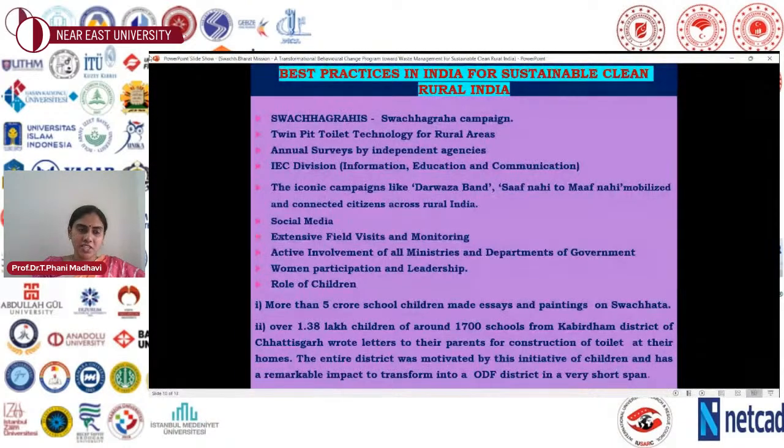Both pits are connected with a junction chamber at one end, and the pit walls have a honeycomb structure, and the bottom of the pit is earthen. Depending on the number of users of the toilet and the size of the pit, it will vary. The capacity of each pit is kept for a duration of 3 years. So the first pit, after it gets filled in about 3 years, will be blocked at the junction chamber, and the second pit will start to operate.